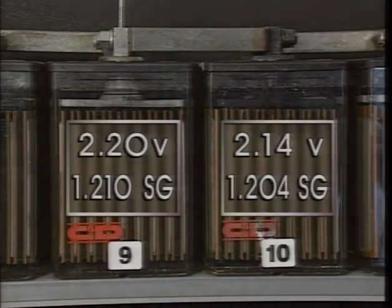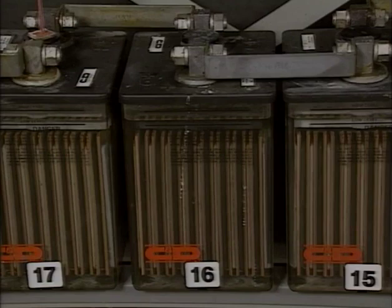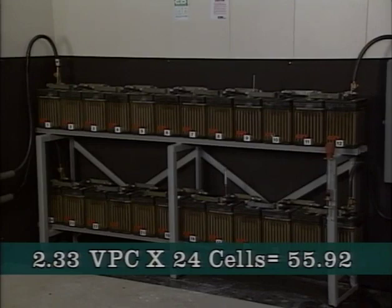In general, if the voltage of any cell falls below 2.13 volts, or if the specific gravity of a cell falls 10 points below its full charge value, an equalizing charge should be given to the battery. The equalizing voltage setting and the number of hours that the equalizing charge is applied are typically specified in cell manufacturer instructions or by company procedures. A general equalizing voltage guideline for lead antimony and lead calcium batteries is 2.33 volts per cell. This is multiplied by the 24 cells in the battery, for a total equalizing output voltage of 55.92 volts.